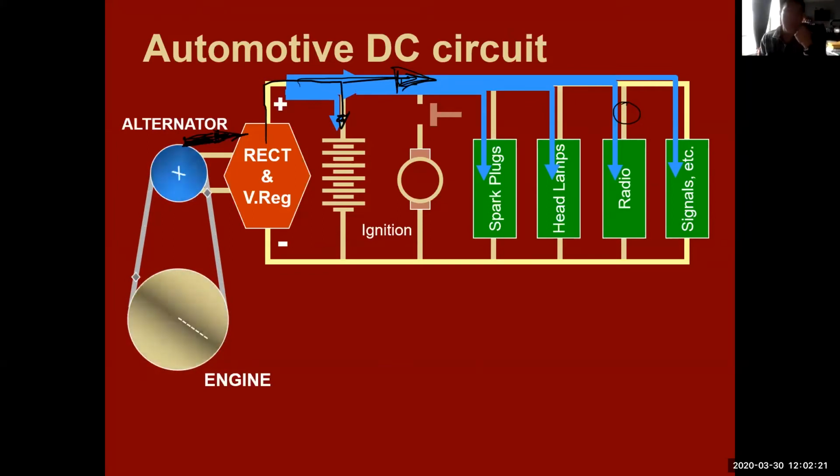die first. Because doesn't the alternator make sure that everything's running electricity-wise? So if your alternator goes bad, that means the battery's just going to drain out. Exactly. So your battery's not being recharged, and now your battery is supplying everything. All right. So the first thing that would go out is your radio, right?